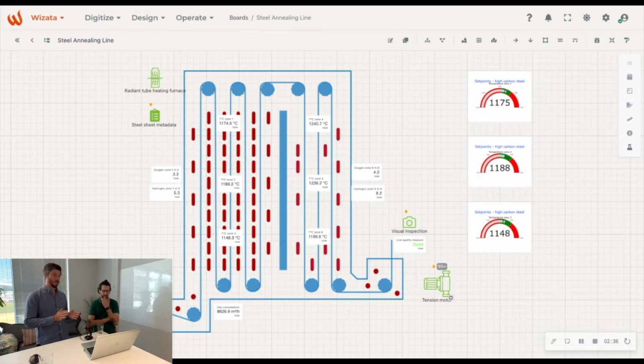The heat is distributed with radiant tube systems, because you also have a specific gas environment that has to be applied to the surface of the steel. So you need a high level of hydrogen, and you need to keep the oxygen level constant as well, to be sure you don't bring surface defects. So the goal is to change the mechanical properties, but we don't want to deteriorate the surface quality. So you need this environment, and the tubes protect the flame from being exposed to this environment that is quite explosive, actually. So that's how the heat is distributed.